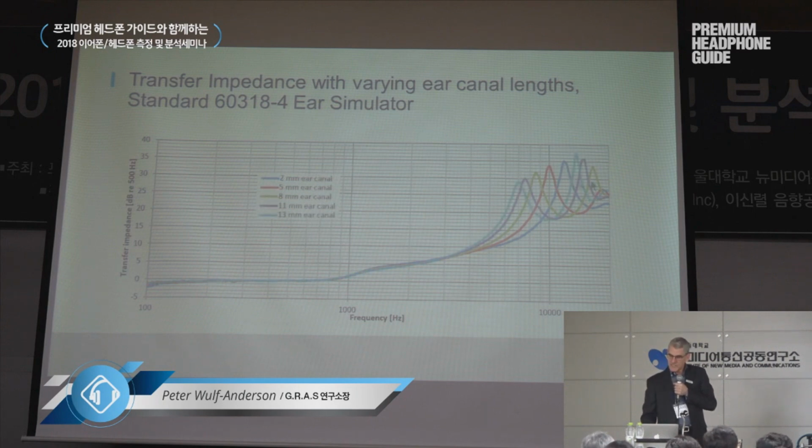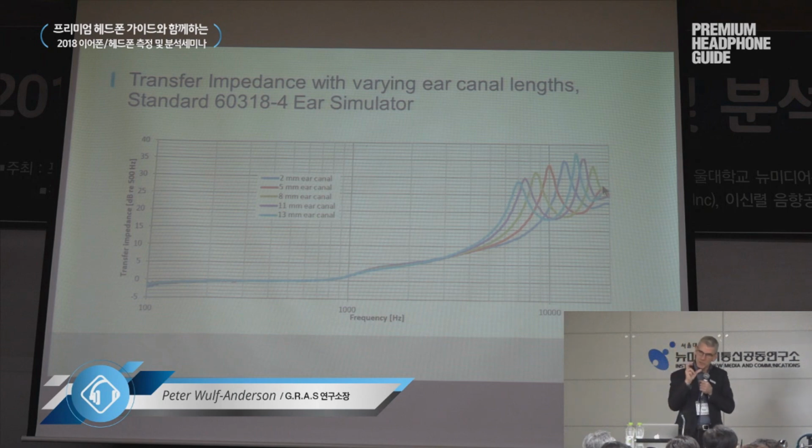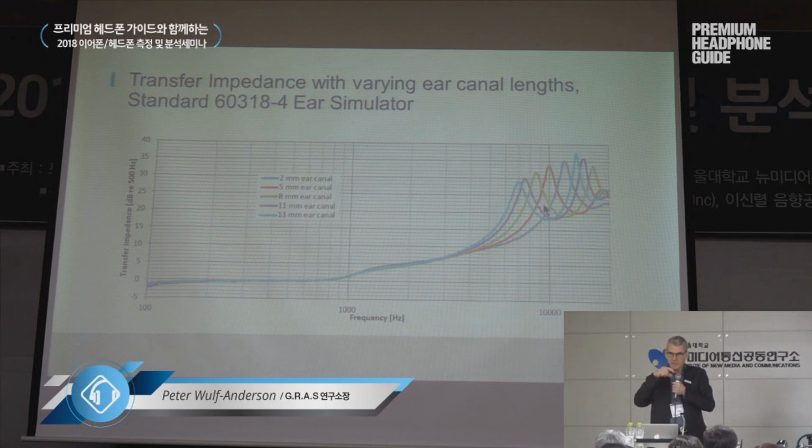So you can see that the resonances move down, and you suddenly also can see the full wave resonance, making it very important to have correct insertion depth of your headphone, especially if it's in ear every time. But also, again, having lots of sharp edges on the resonances can complicate high frequency measurements a lot.